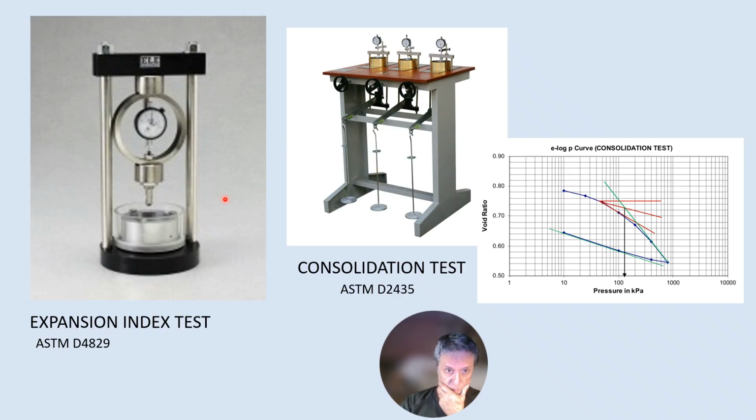Here are other tests. I mentioned expansion with swelling clays. So this is kind of the opposite of a compression test. You put a sample in a metal container, and then you saturate the sample. As the soil swells, it will move this piston upwards, and the amount of swelling will be recorded on this dial.